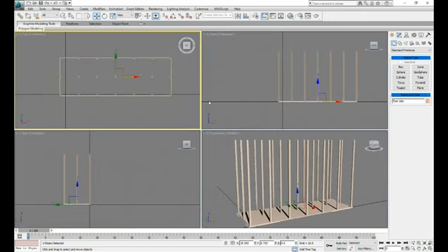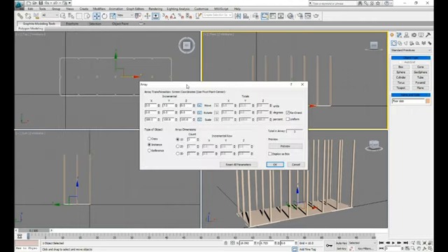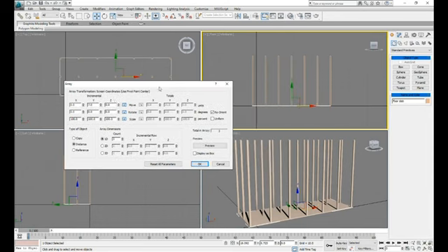Here again, I will click this one, but this time I will go to the front elevation. Why? I want to copy the slab multiple times directly going in here. So this is what will happen. I will click tools again. Array. This time, please leave this one 0. Why? I want that every floor is 3 meters now. Then what I want is count 10. It means I have 10 floor slabs going to Y.